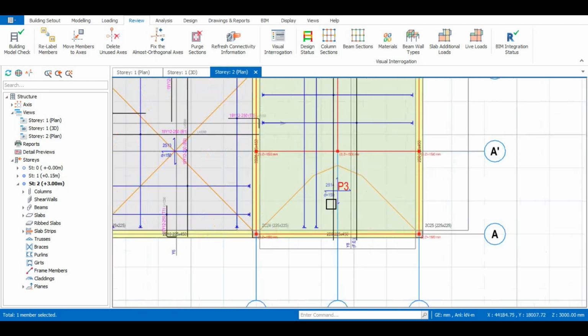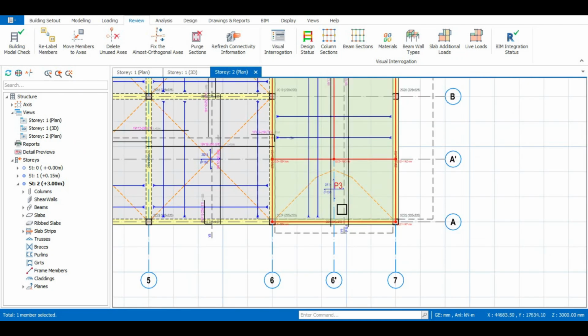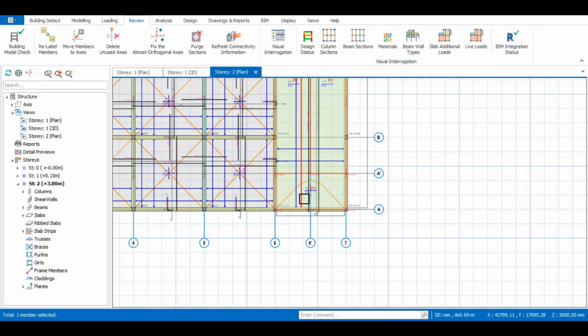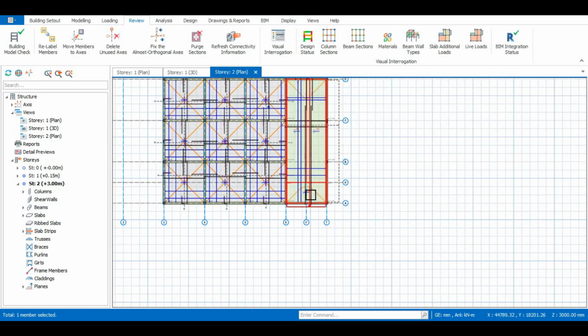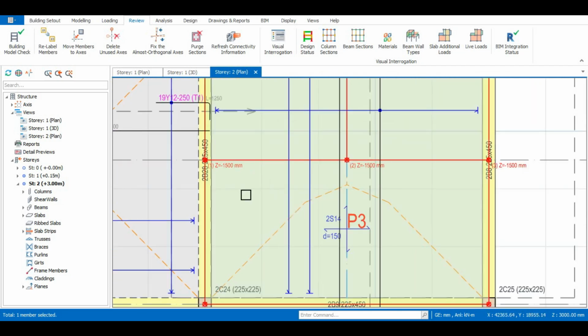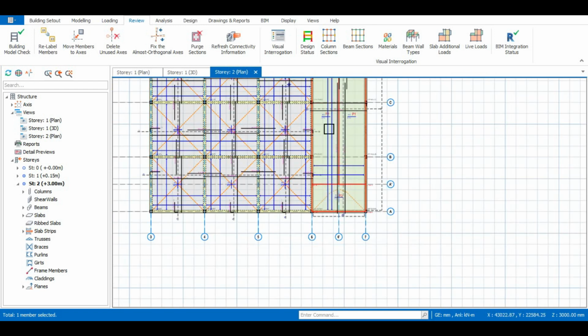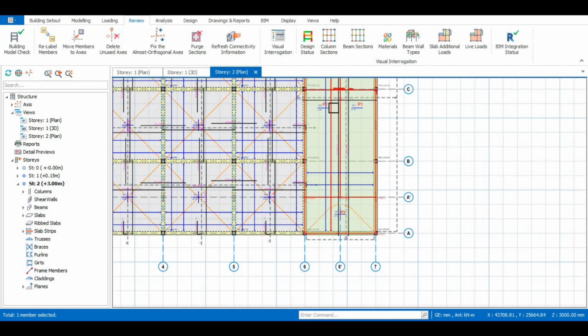Then also for the landing here, you realize that we have 59 going from here to here, for the bars that will be arranged across like this, on the x-axis, on the x strip. So the y strip was what we discussed earlier, that you can divide into two and arrange 10 on one side and 9 on the other, or 10 on both sides, depending on your discretion.